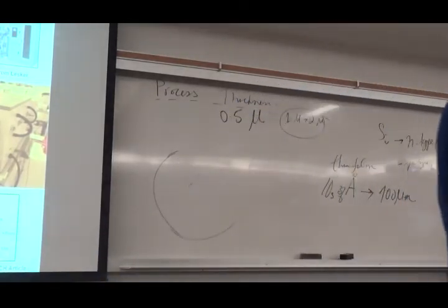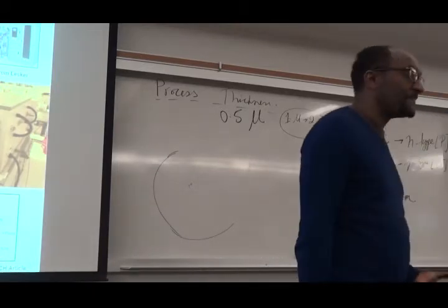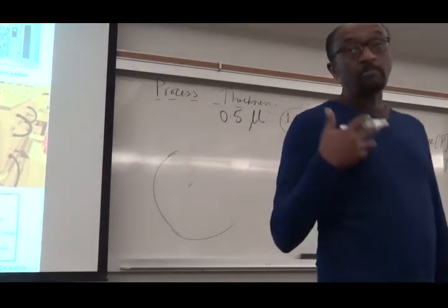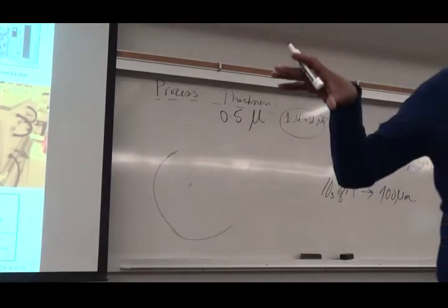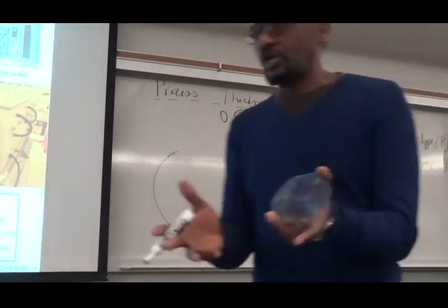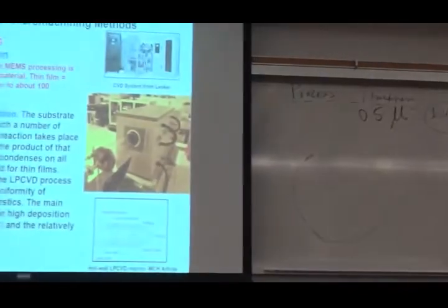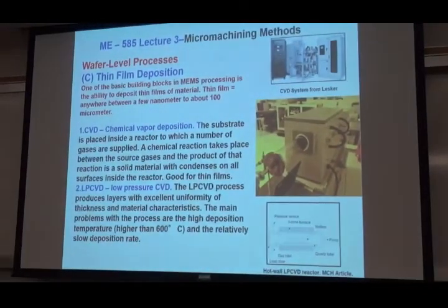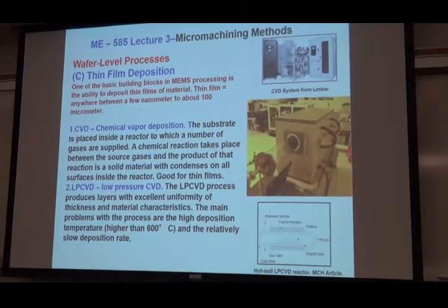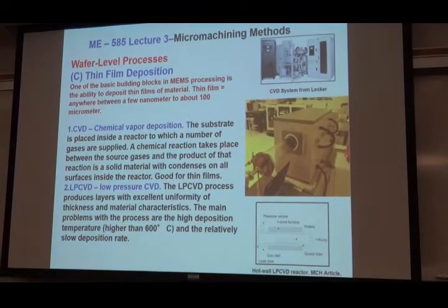So typical semiconductor, because remember I told you, like metal, all that much gold, I mean, you're not going to put 100 micron. So typically we put only 10 nanometers, 20 nanometers, and so on. But now we're using more and more polymers. And remember, at San Diego State, our distinguishing feature in terms of microfabrication is we marry silicon with carbon. A very unusual marriage, but it works. So when you put polymers, then you go all the way to 100 nanometers, micrometers. So I really want you to remember this, okay? So that's your thin film.